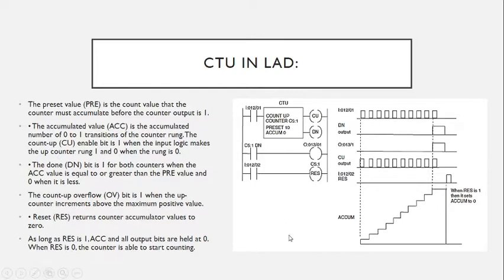By running this example, we will see how the counter works, and we are going to turn on and turn off the input to test the counter. How do we do it? In the simulation scenario, we just right click and do force on and force off, force on and force off. We continuously do that, not too quick, in a good time fashion that goes well with the scanning time and everything.